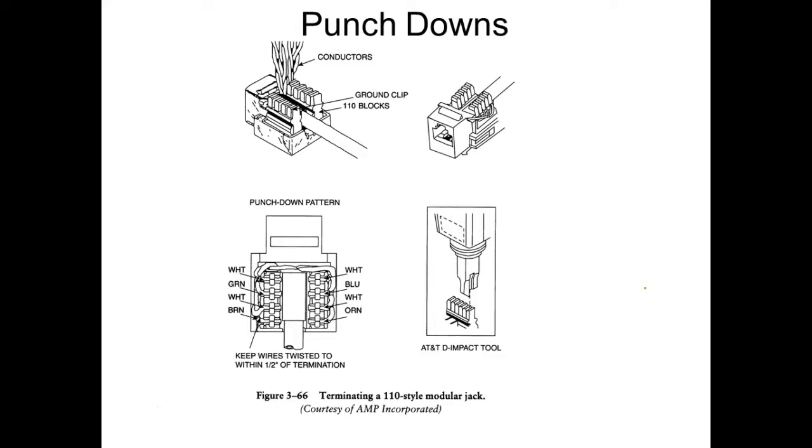But that guy's got a switch on it. So I could use a straight through cable from the PLC to the switch, and then the switch to my computer, because I'm going through a what? I'm going through a DCE, right? That makes sense. So if I went that route, I would have to use a straight through cable. If I went directly to the PLC, I would have to use a crossover cable. That makes sense.